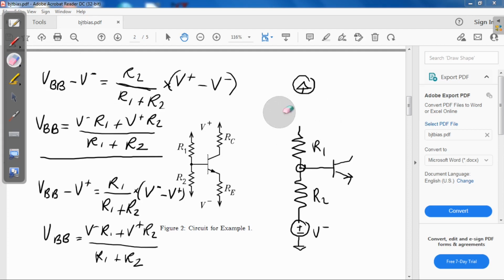So this gets shorted. Okay, the other one, same thing. So that gets shorted. Okay. So now you have to compute the resistance between this point and that point. But remember that this is ground, so it's actually R1 in parallel with R2.